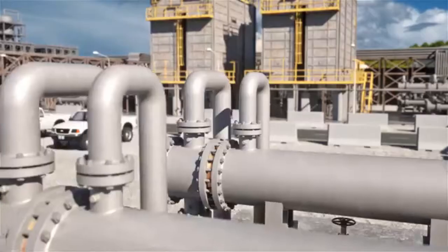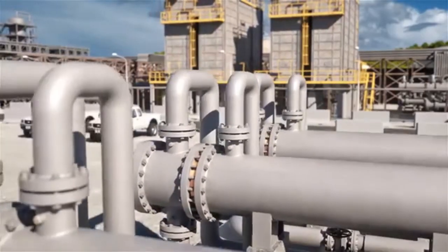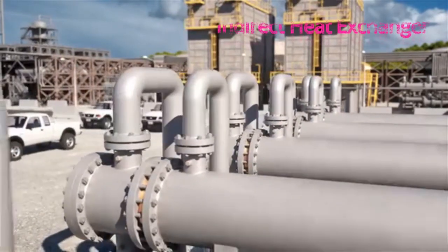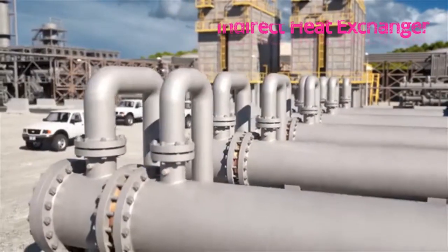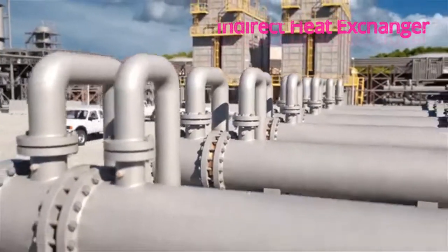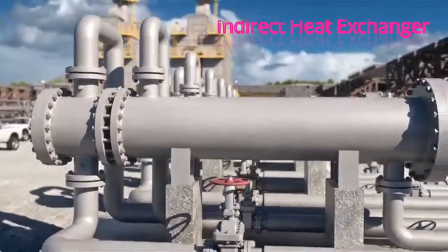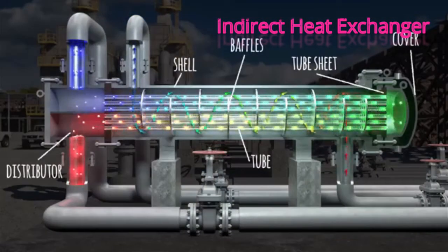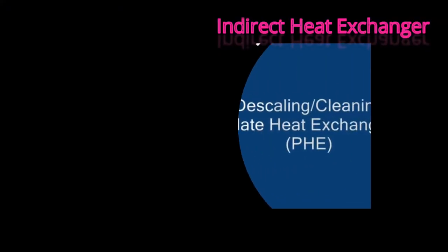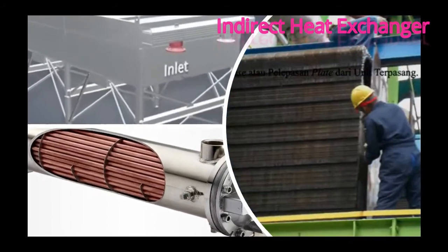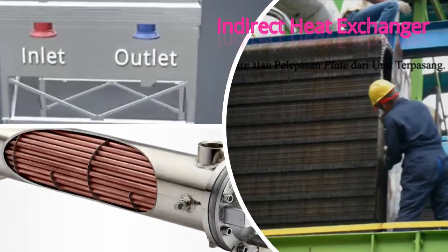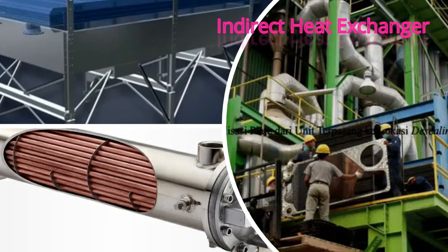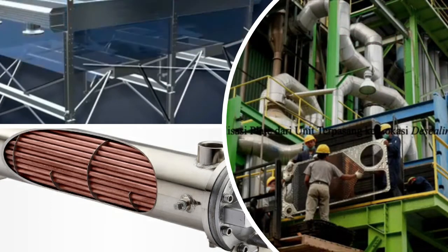2. Indirect heat exchanger, where both media are separated by a wall, through which heat is transferred. In this type, heat from a fluid, a liquid or a gas, passes to a second fluid, another liquid or gas, without the two fluids having to mix together, or come into direct contact. Indirect heat exchangers are available in several main types, for example, plate, shell and tube, spiral, etc.